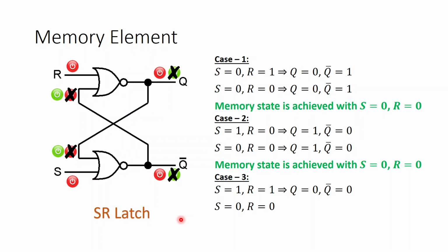Now from the practical viewpoint, this system will not show up this instability. Why? This is unstable, that is what we said. But from the practical viewpoint, this system will not show up the instability, because you must understand that there is some propagation delay of these NOR gates.